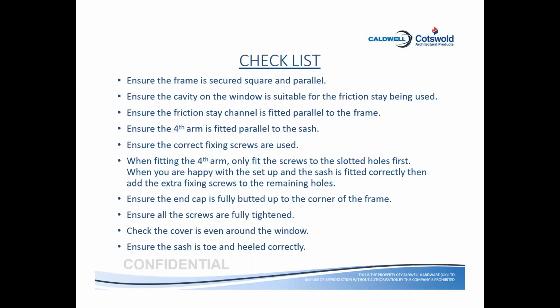The outer frame needs to be very square and parallel, especially when the civil work is disturbed or some architectural challenges are there. You need to make sure that your window's outer frame is fixed very correctly, square, parallel, and the diagonals are correct after fixing. Nowadays, to check this, I have seen in Bosch some small device, 5 to 7,000 it comes.